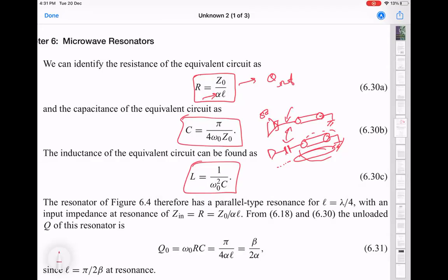What you will see is that the very fact that it's 100 micron by 100 micron means that piece of metal has some inductance associated. What that effectively means is that at sufficiently high frequency, that L and the C will resonate to give you a resonance. So you sort of get a free resonator. You're trying to make a capacitor, but you ended up making a resonator. But as long as that resonant frequency is much higher than the frequencies of your interest, it's still a perfect capacitor for your purpose.